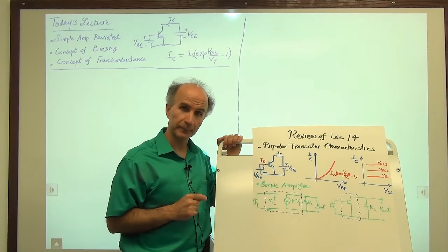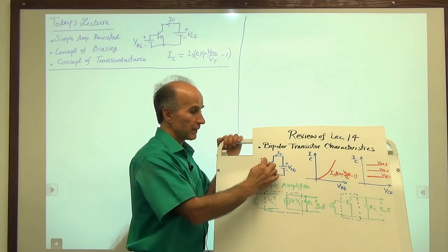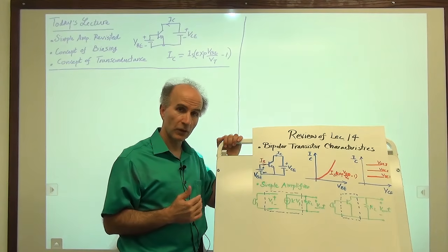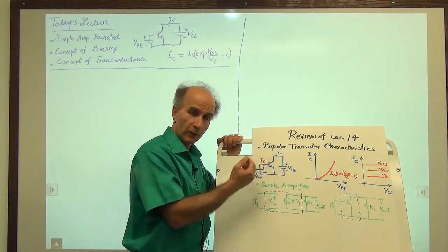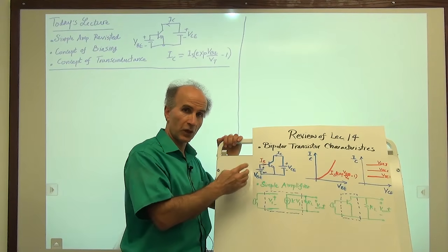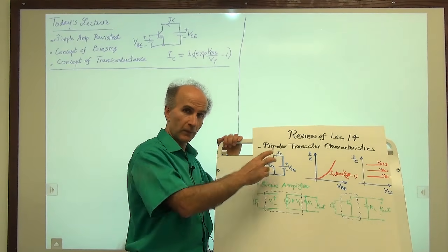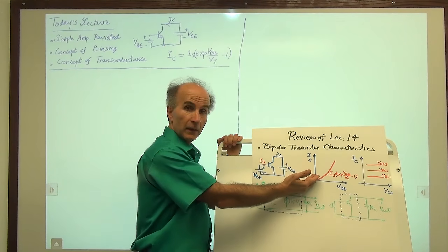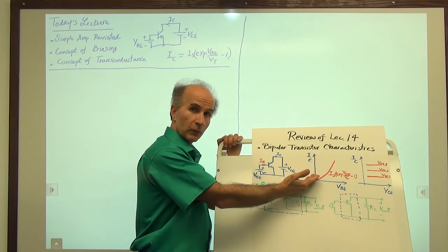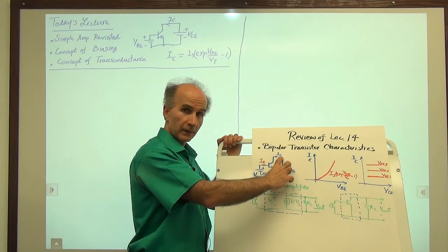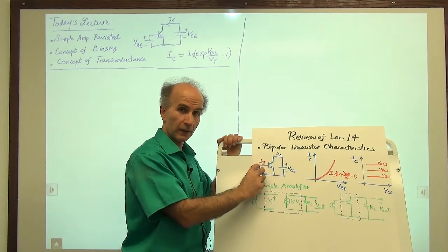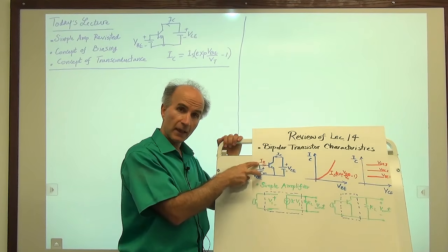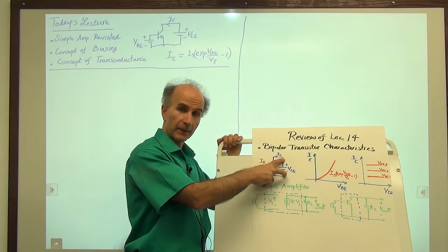Now, because the bipolar transistor is a three-terminal device, we can measure the currents, for example, when we change one voltage, but we have to keep the other voltage constant. So in this test, the collector emitter voltage, this one, is constant, but it's this one that's changing. Now we can go the other way around. We can keep this constant and change this one and see what happens.